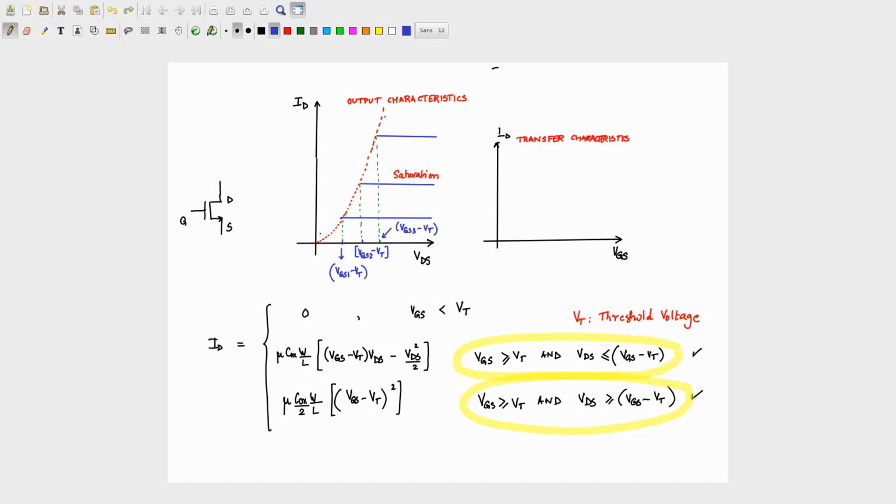Alright. Now we are going to look at the scheme wherein you have VGS greater than VT, but VDS less than or equal to VGS minus VT. How do you think the current voltage characteristics are going to look in this regime? Right? So you know that at VDS equal to 0, the current effectively goes to 0, so I have to be here, and you know that at this limit you have to be at this point, so basically you can connect these two via a smooth curve.